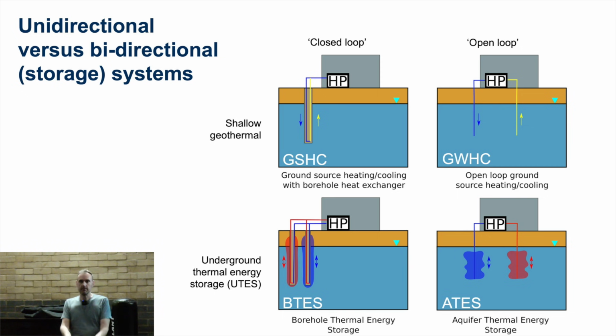What if we reuse that? So instead of just leaving it in the aquifer, what if I store heat in the summer and produce that back out of the aquifer in the winter, and then store that waste cool in the aquifer, and bring it back out in the summer? And that's exactly what we do in underground thermal energy storage. So this is the energy storage bit, right? What I've talked about so far is geothermal. This is the energy storage bit. And what I like about this is it's more efficient than just leaving the heat or cool in the aquifer after we've used it, because we can bring it back out and reuse it.